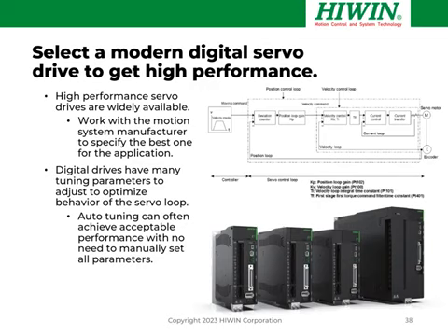Now, the digital drives that are out there in the market today have a lot of different tuning parameters, lots of adjustments, ways to optimize the behavior of a system. It can be daunting, but some of the advances in computing technology mean that they often include an auto-tuning algorithm that you can use, which will often achieve quite acceptable performance with no need to manually set all the parameters. You might need to tweak a few, but it really reduces the need for servo expertise.